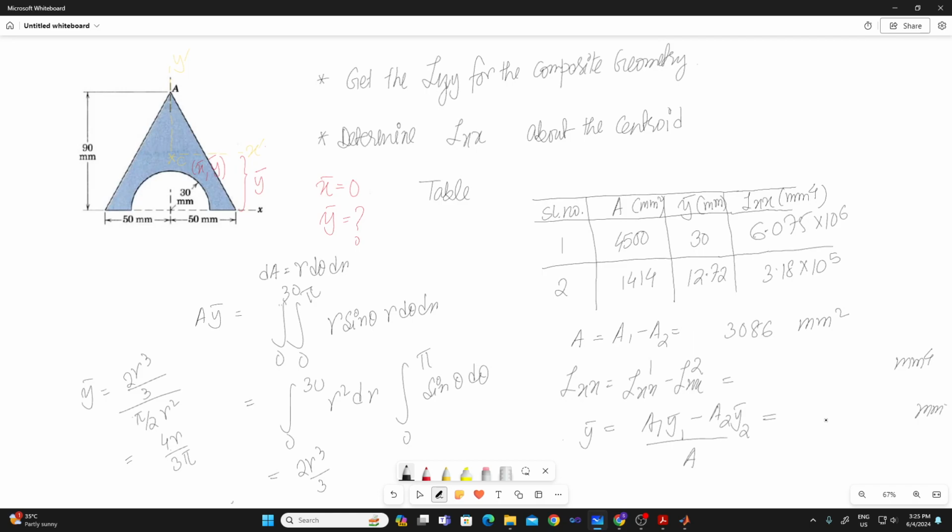So that is 37.91 millimeter. 37.91 millimeter, correct. Okay, then, you basically took out some material from the region closer to the x-axis, so the centroid shifted upwards. Earlier it was 30 millimeter, but because you took away some material closer to the x-axis, the centroid actually went further away from the x-axis. That's what it looks like.